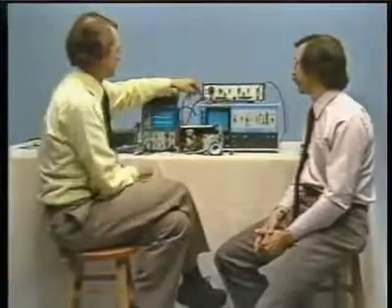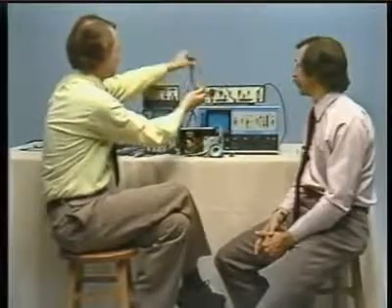What I'd like to do for a last experiment is, what we've been doing at this point is taking something that's coming in over the airwaves, as they used to say, and simply viewing it. I'll turn this off for a moment. What I'd like to do now is generate our own radio frequency signal, tune it up so this radio is going to hear it, whatever that means, and display it here. What we're going to do then is use the audio oscillator along with the amplitude modulator, and we're going to take from the output now the lead here, and this will act as the antenna.